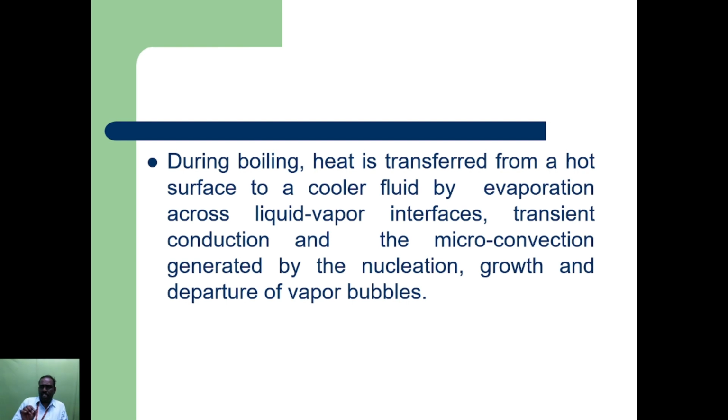During boiling, heat is transferred from a hot surface to a cooler surface by evaporation across the liquid-vapor interface, then by transient conduction, and third by microconvection. First, evaporation from the hot surface to the cooler surface across the liquid-vapor interface. Second is transient heat conduction. Third is microconvection generated by nucleation, growth and departure of vapor bubbles. Attachment and detachment of the bubbles play a great role in heat transfer.